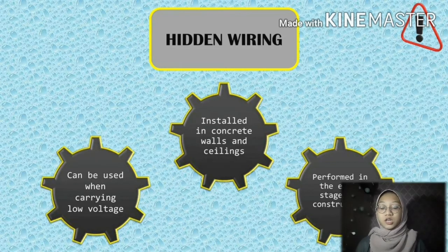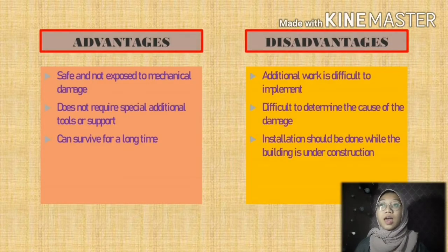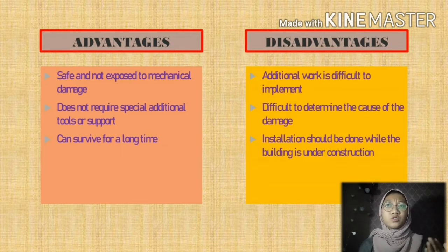Advantages. First, safe and not exposed to mechanical damage. Second, does not require special additional tools or support. And third, can survive for a long time. The disadvantages. Additionally, the work is difficult to implement and it's also difficult to determine the cause of the damage. And the installation should be done while the building is under construction.